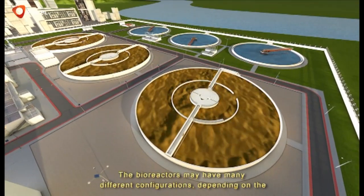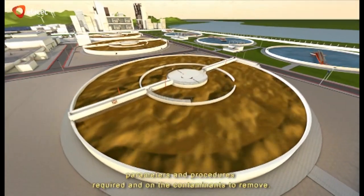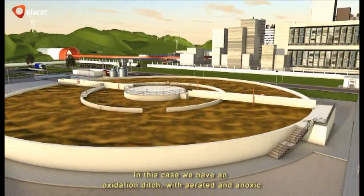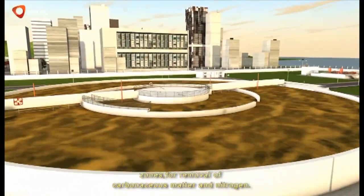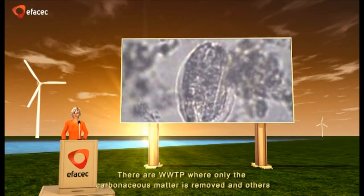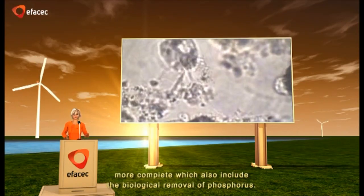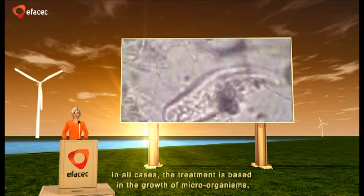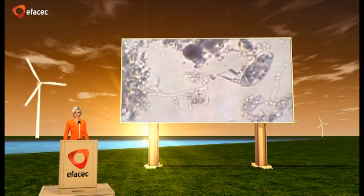The bioreactors may have many different configurations, depending on the parameters and procedures required and on the contaminants to remove. In this case, we have an oxidation ditch with air and anoxic zones for removal of carbonaceous matter and nitrogen. There are WWTP where only the carbonaceous matter is removed, and others more complete, which also include the biological removal of phosphorus. In all cases, the treatment is based on the growth of microorganisms, referred to as biomass, which will feed on the water contaminants.